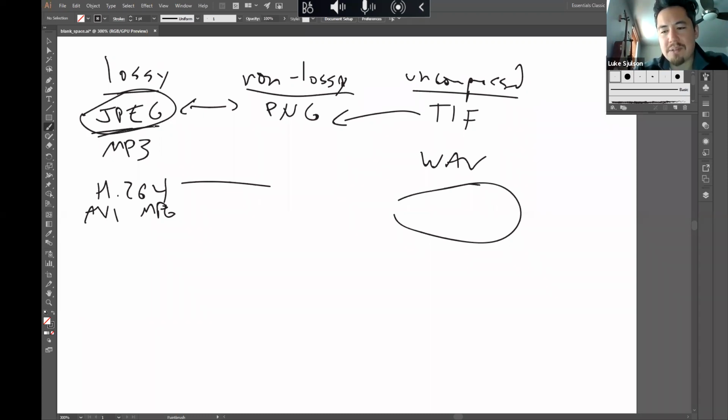But if you have natural scenes, the way JPEG works is that it does a discrete cosine transform, which is like a Fourier transform except it's real valued. Then it only stores the coefficients for the sinusoids that have the highest magnitudes, and discards all the low magnitude ones. Because natural scenes have low spatial frequencies across objects and high spatial frequencies at boundaries, only some spatial frequencies are relevant in natural images. So you can discard all those other spatial frequencies and still get a really good reconstruction with a huge compression rate.